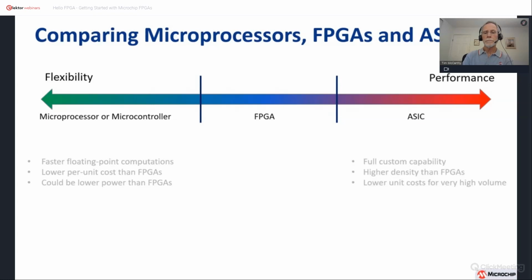An FPGA offers a compromise between application-tuned performance of an ASIC and flexibility of a general microprocessor. Compared to a general-purpose processor, FPGAs have lower latency. Latency is the time between the input and the response. One of the main reasons for this low latency is that FPGAs don't depend on an operating system to implement tasks. FPGAs have flexible I/O assignments. The logic elements in an FPGA can be connected to almost any pin. Microprocessors have fixed pin assignments.